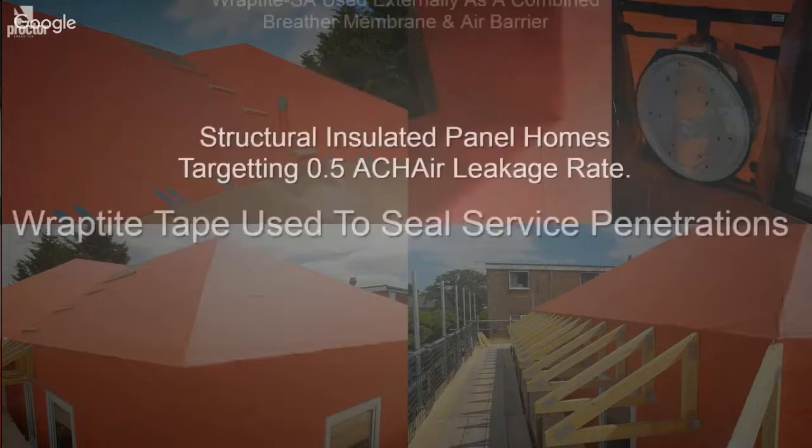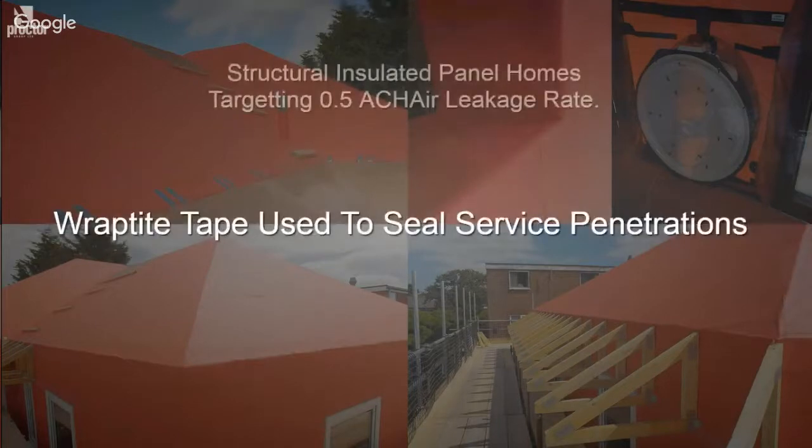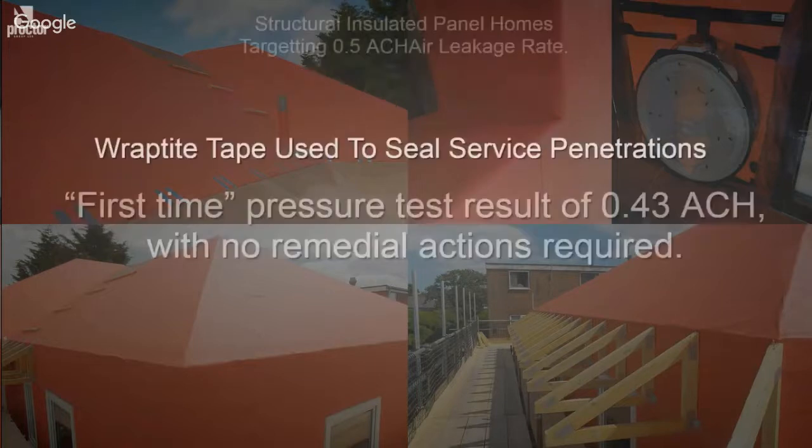So these panels were fully wrapped with the Wraptite-SA vapour permeable membrane, and at the joints, the tape version of this product was used to seal any junctions, openings, services. And what that does is ensure an entirely airtight envelope without leading to any issues, for example, with trapped moisture.